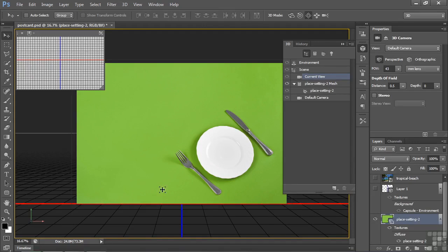Now, when you create a new 3D object by using that panel, every object you create, except for a postcard, has a light automatically added to that layer. But postcards don't. That's because if you add a light to a postcard, it almost always blows it out and makes it too bright. But that doesn't mean it's not being illuminated. It is. It's being illuminated by an image-based light. Let me show you what I mean.